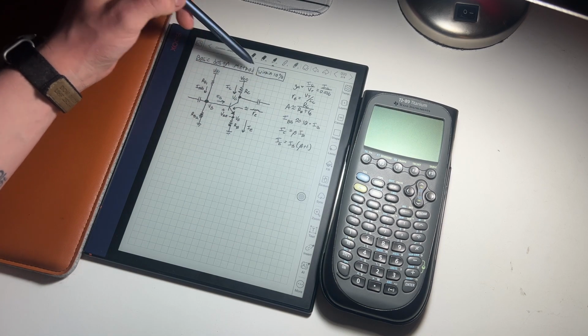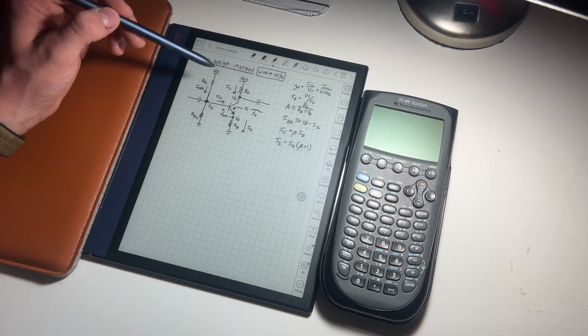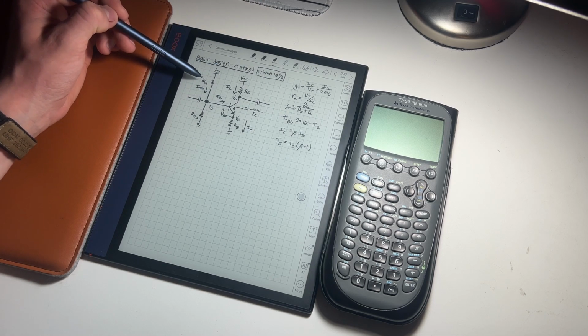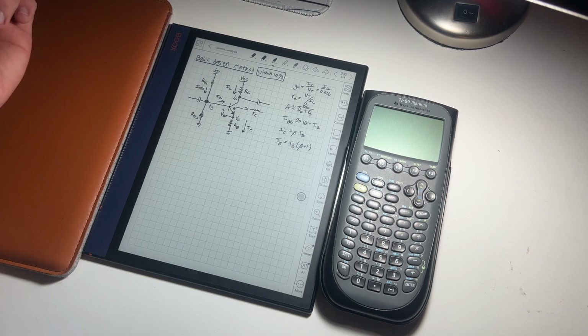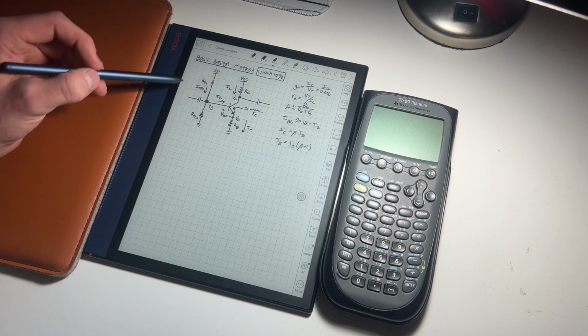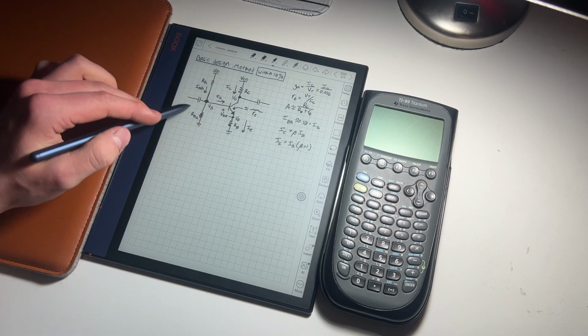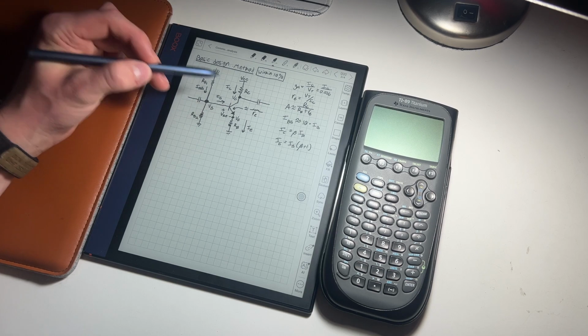So now we're going to look at this circuit here and these equations here. You can see in this circuit I have 4 resistors, RB1, RB2, RC, and RE. And these are going to set up the Q point or the DC operating point as well as the gain of this transistor amplifier. And then we have the transistor right here.